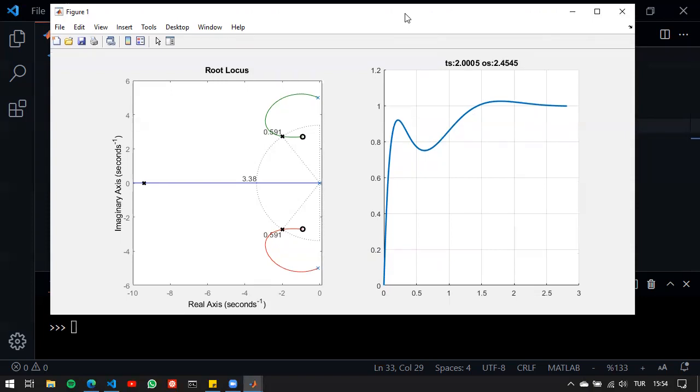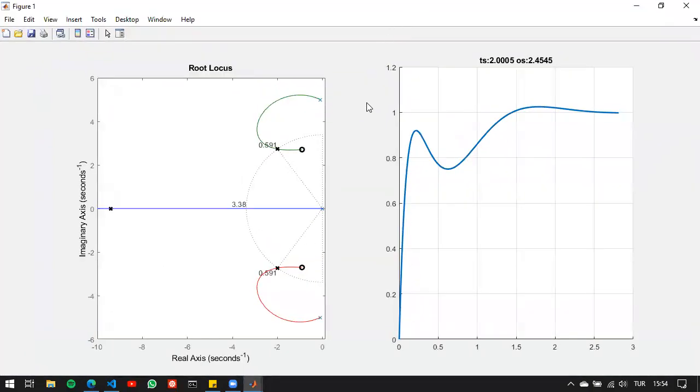So this is an example which shows us that even though we are satisfying the settling time pretty well, we don't really have the best overshoot here, because we were looking for 10%, but we have 2.4% overshoot, which is not ideal, but we can maybe live with it. But the fact that this system has an odd response in the transients, and that the dominant pole placement strategy does not work here, is important to note.